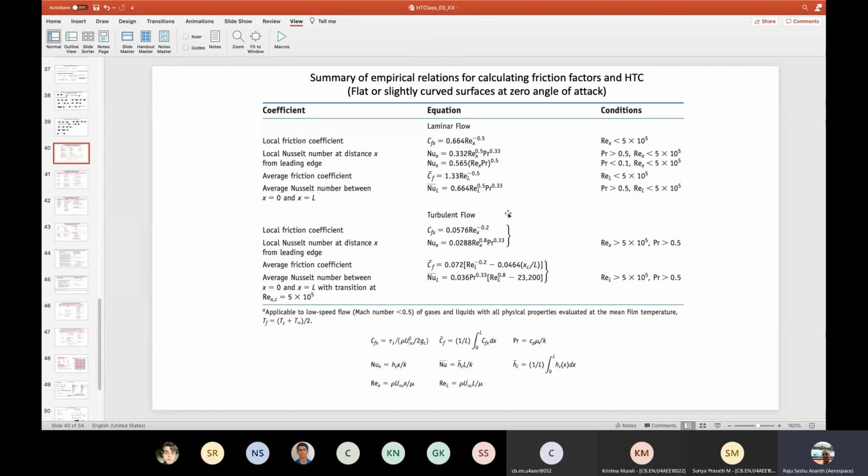Okay, in the case of turbulent flow, which we haven't done here, you can use the Reynolds analogy for turbulent flow, except the velocity profile, they assume the 1/7 power law, but there are some issues with the boundary conditions, but they ignore that. Theoretically you can evaluate using the Colburn Reynolds analogy, but the empiricism is basically what we have found out.